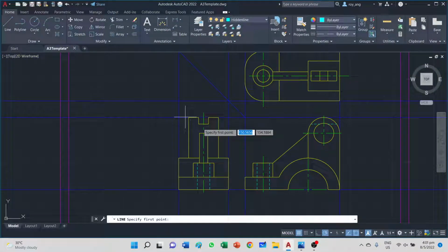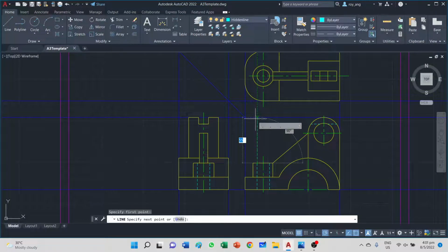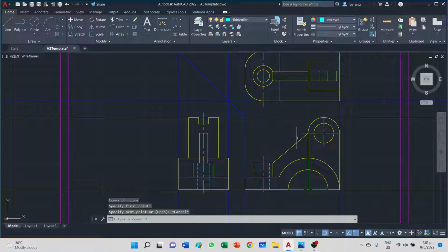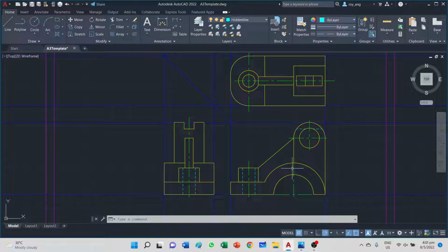And I have my hidden line. Now if you're not sure, if you're feeling a bit insecure, when you project up, you realize that it matches the hole in the plan view. So you're good. Now what is the next hidden line that you will see? The hidden line that you'll see on the end view will come from this feature. So we look at each feature one by one, and we see where the hidden lines are. There should be one hidden line here because there is a hole that goes right through. So what we do is we project it across.